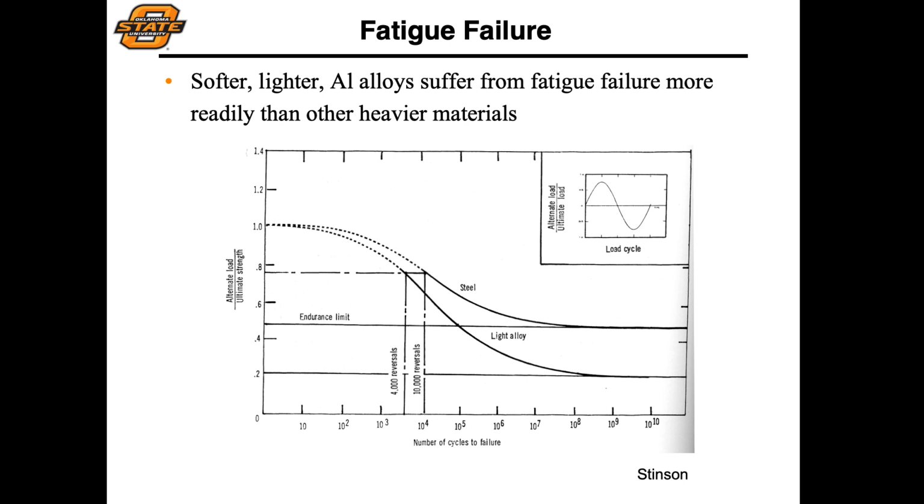The best common everyday example that I can give is a paper clip. Take a paper clip and think about, well, I want to snip this paper clip in two. You go to get a set of shears. Think about the energy that goes into snapping that thin paper clip in half. But if you want to do that more easily without using a mechanical implement, then just do some cyclic loading. Typically in about 10 cycles, you'll be able to take that paper clip and fail it.